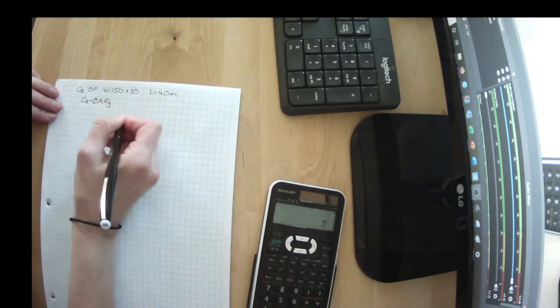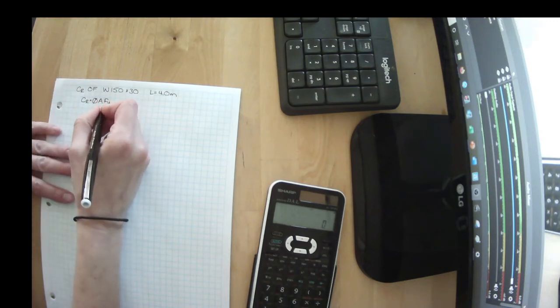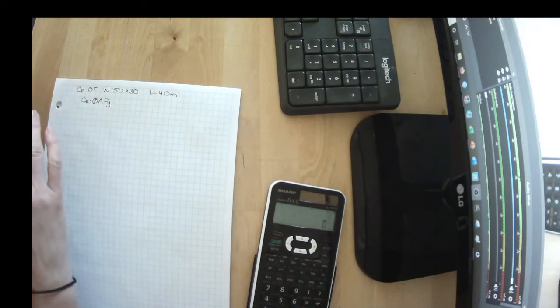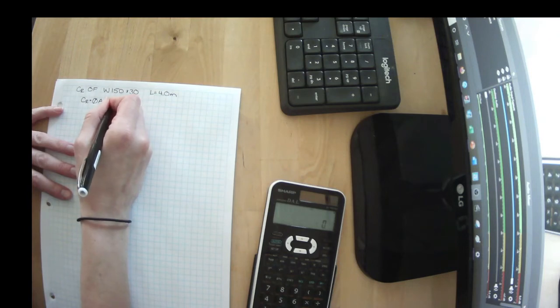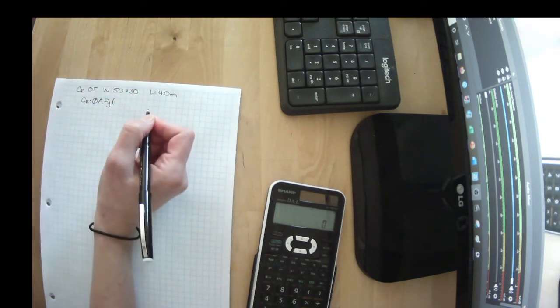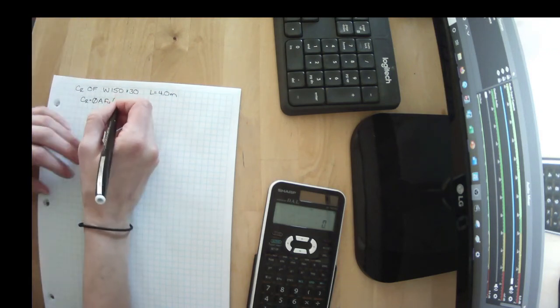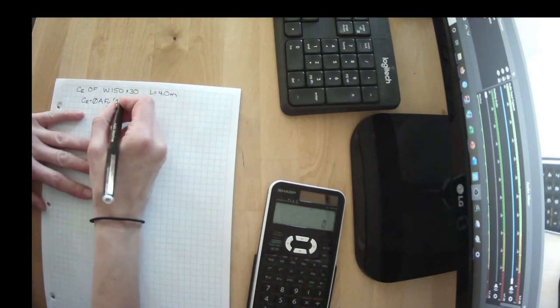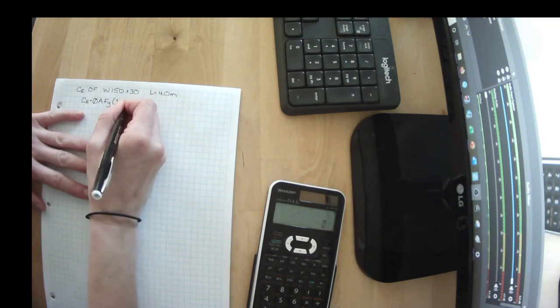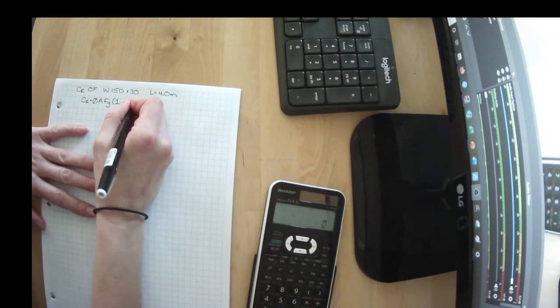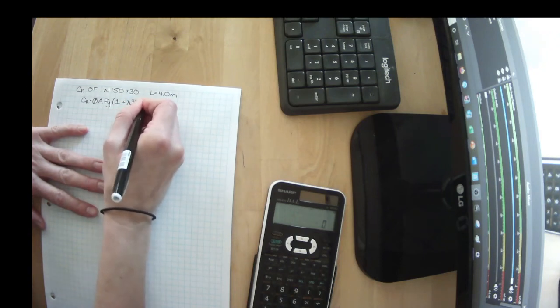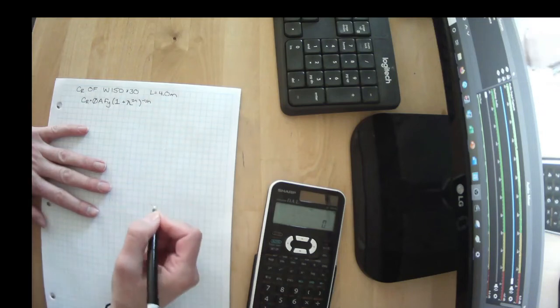Our reduction factor times our area times Fy, and that governs if our column's a little baby tiny short column. But if it's tall, and we don't know what short versus tall means to a column of this size, so we'll calculate it out. But if it's really tall, buckling governs. And we know that this portion of the equation is derived from the critical buckling load.